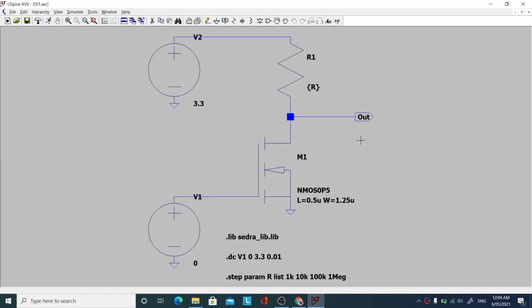To try to justify what we just said, let's now go back to our original circuit, and we're going to add a capacitor to the output here to see what we get. So if we were to connect this to a logic gate, we believe the input to a logic gate looks like a capacitor, so let's just add a capacitor here and see whether or not this behaves like a resistor. If this behaves like a resistor, then when we connect this to a capacitor, we should get a charging curve as before. We need to make a number of changes.